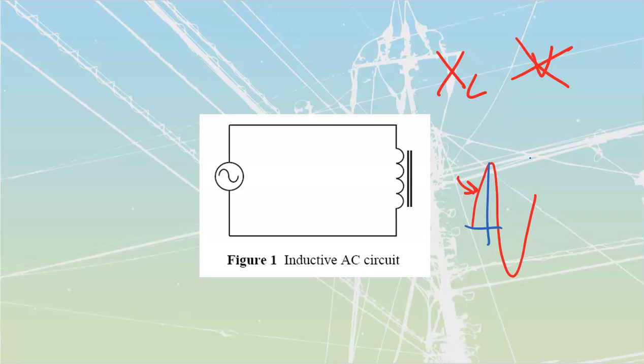And because I've changed the amount of time to react, my inductive reactance, my XL, is going to double, because I'm just going to be clamping down. I've got the same inductor, I don't have the same amount of time to get stuff done inside of there. So frequency is going to be a direct relationship. My actual inductance, the L value that I'm going to have to this one.